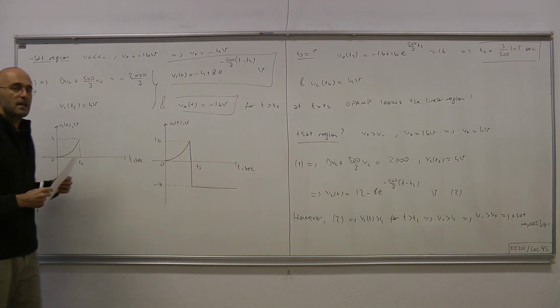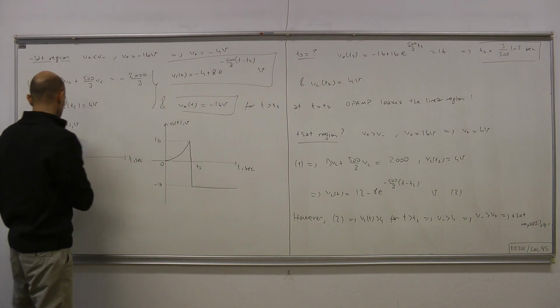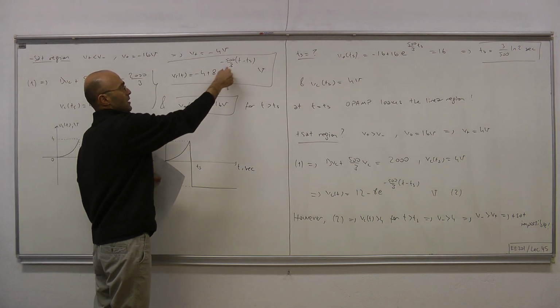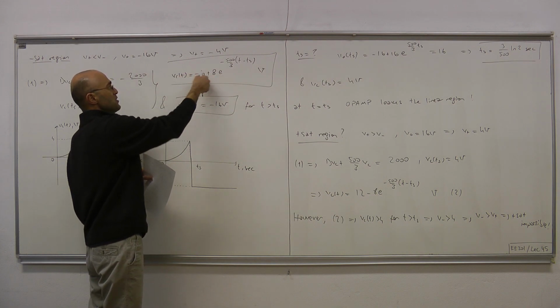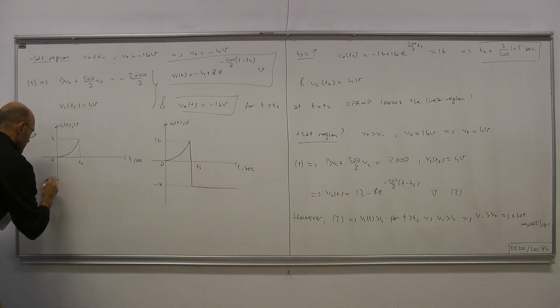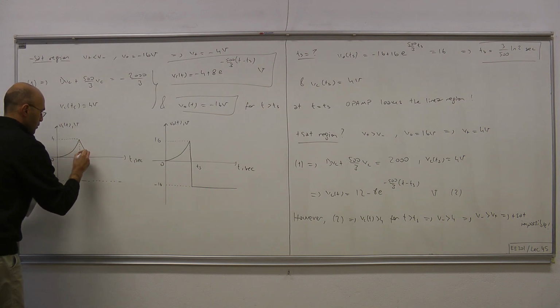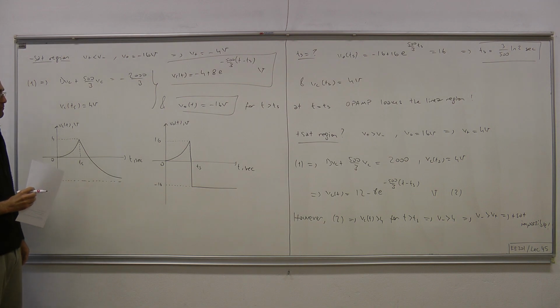And as for the capacitor voltage, this is what we have obtained. We started at 4 at t equals Ts, and what we are heading toward is, now this exponential term is becoming smaller and smaller as time goes on, therefore VC(t) is converging toward that constant term, which is minus 4. Okay, so we were expecting a curve like this for VC(t).